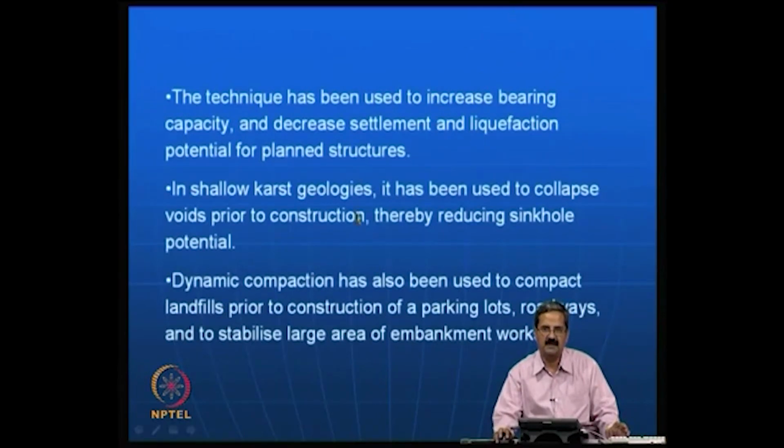As I just mentioned, this technique has been used to increase bearing capacity and decrease settlements and liquefaction potential for plant structures. In fact, this is one of the very important applications. In shallow karst geologies where the soil has a tendency to collapse, it reduces the voids prior to construction, so that the sinkhole formation potential is reduced.